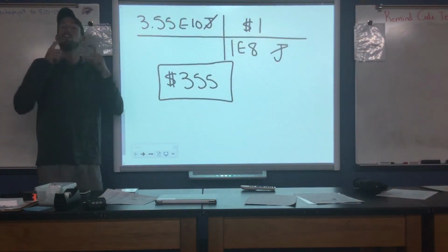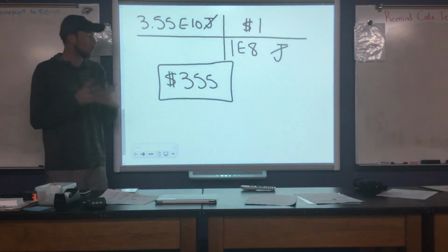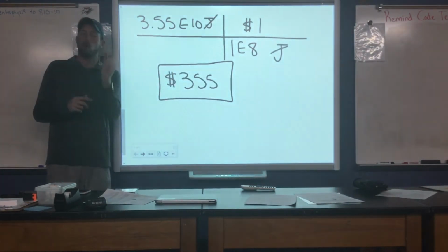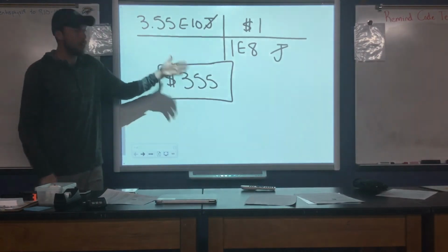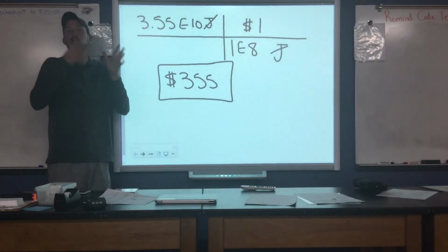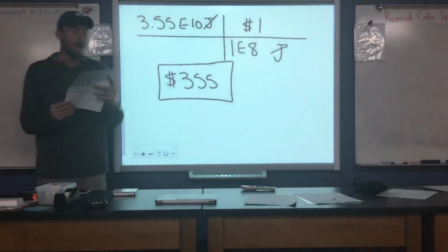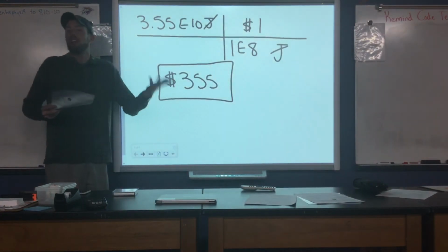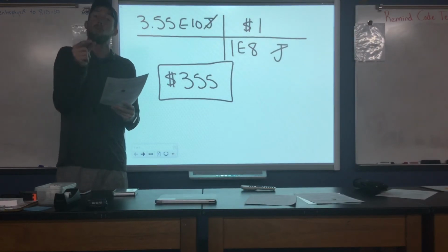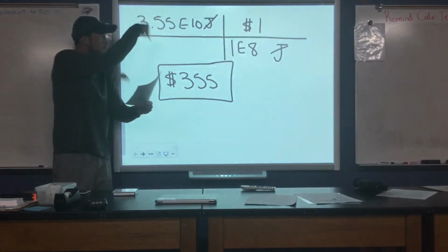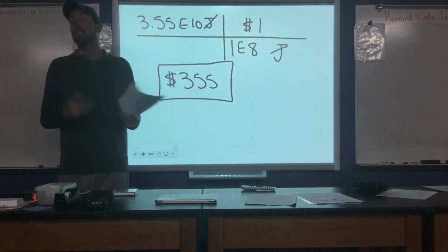This number would describe very standard, really older types of windows. Most windows that you probably have in your home or wherever you live don't actually have one single pane of glass. Most of them are double pane glass, and that's what we're going to look at here in just a moment. So that number is very high, but these are for very older styles of windows, which most people don't actually have anymore. So looking at the backside of the group problem, we're given a few different windows to look at. These here are actually windows that have a small air pocket in between, and that air pocket is designed to drop down the heat transfer rate, make it harder for the heat to move through the window so we're not losing as much energy.